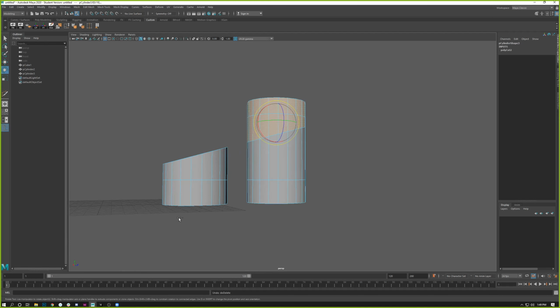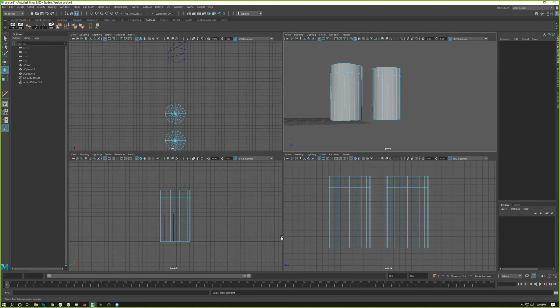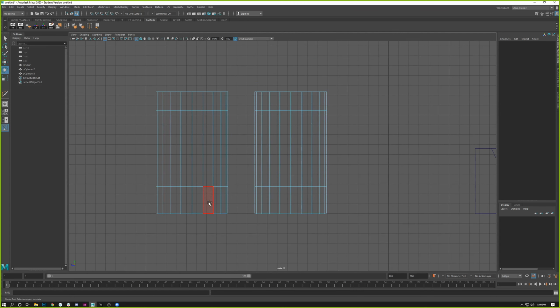Now that tool, I believe also, I might be incorrect about this, if I hit Control Shift X and start dragging, if I hold down Shift, it does lock in increments. That looks like 15-degree increments to me. And this can be changed in the tool settings, which I haven't talked about, but just remember that, and I'll talk about the tool settings probably very shortly.